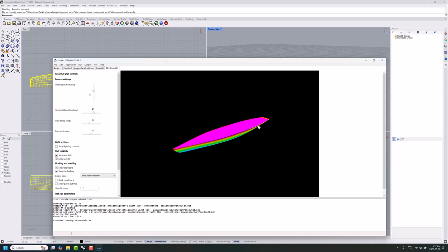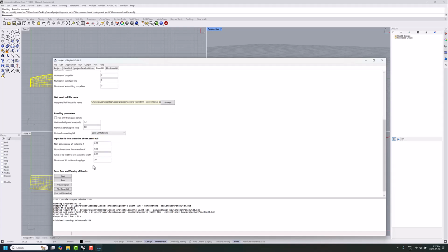All that this is doing is a numerical structure to suppress any wave parameters that appear inside the hull through the calculation of the wave radiation and diffraction effects. It just takes a second, and it's well worth it for significantly increasing the quality of the calculations. And that's it. I find the default settings work pretty well.